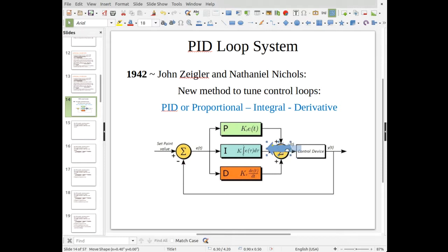to that. It'll basically keep adding those errors up, and they'll build up and build up and build up until it actually pushes the system hard enough to drive the steady state error to 0. All right, so that's why we want an integrator.